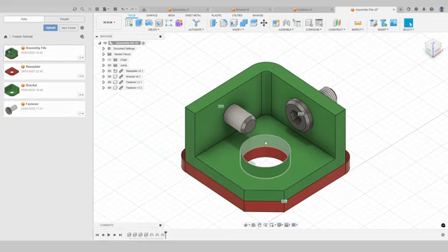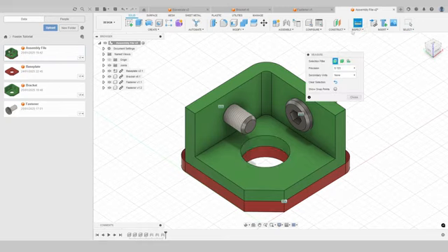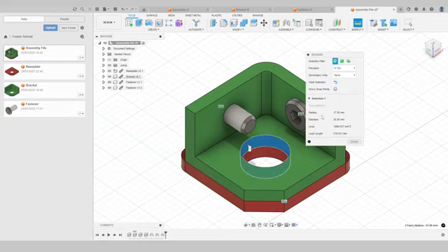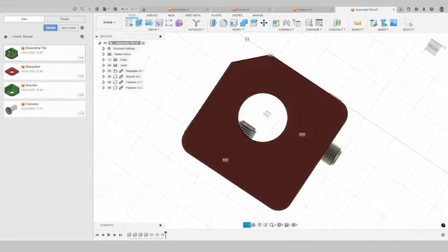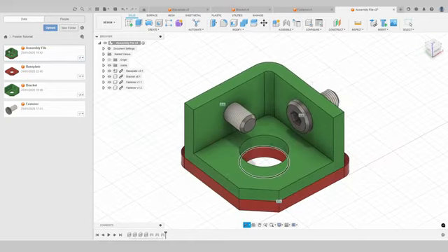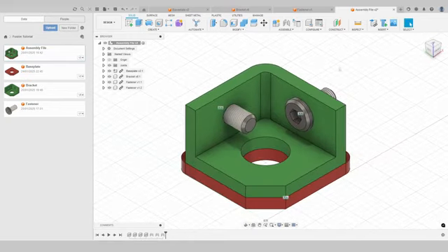And then we can see visually there that our hole has increased. And again, I'm just going to double check that. Click that geometry and again, diameter 35 mil. And it's the same diameter now as the 35 mil, which was what we did for the base plate. A few edits that we can do in assemblies.